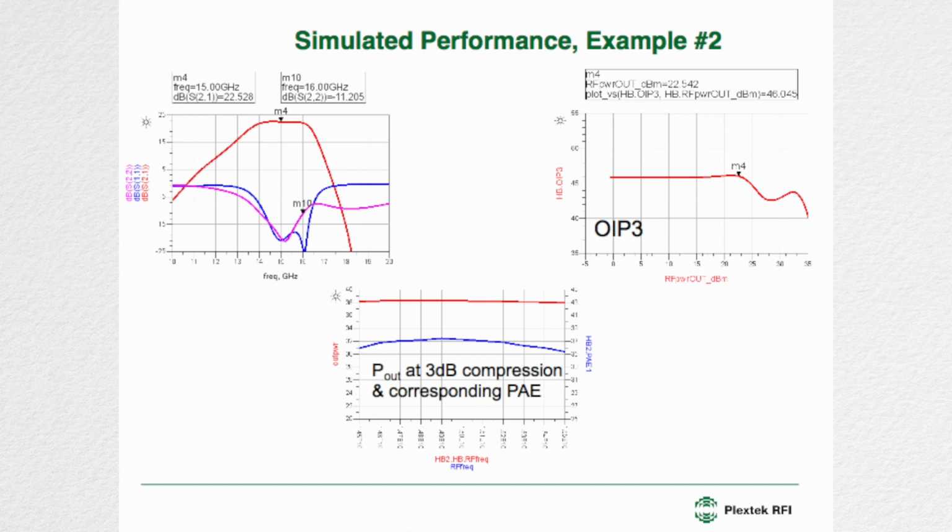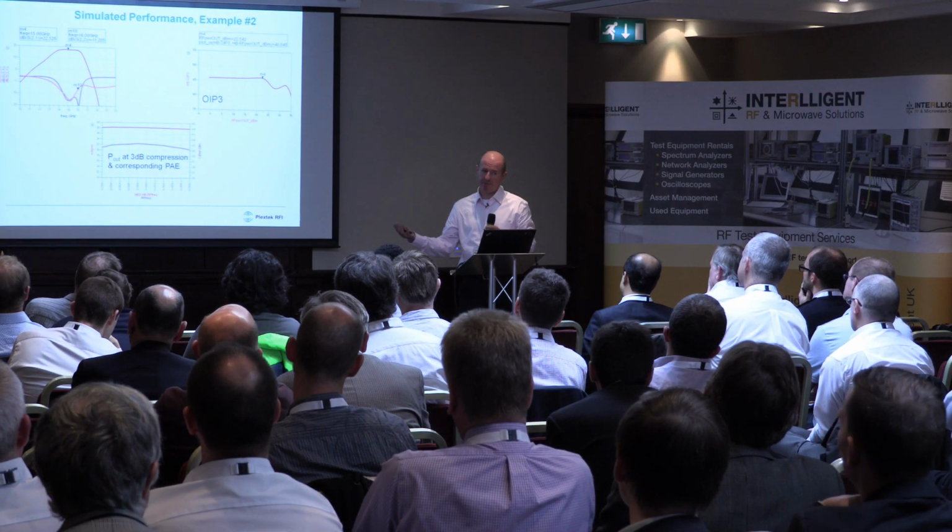When you look at GaN PA MMICs that are commercially available, you'll see that the output power is quoted at a wide range of compression levels. The highest I've seen is 10 dB. So they could say it's a 10-watt amplifier, and when you look at the datasheet, it's 10 dB compressed. We think that's a little bit over the top. I think 3 to 6 dB is reasonable.